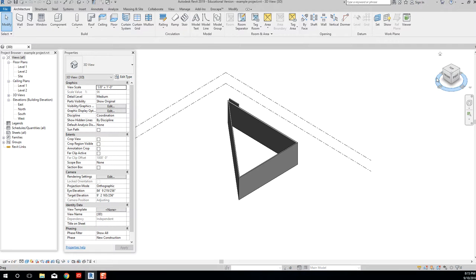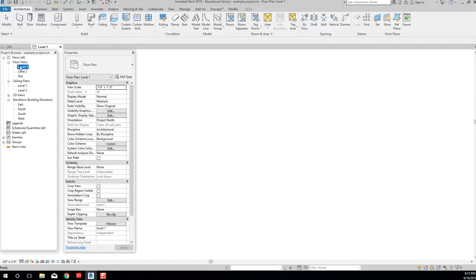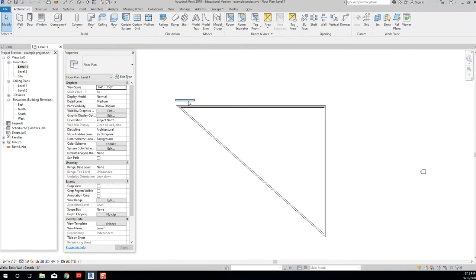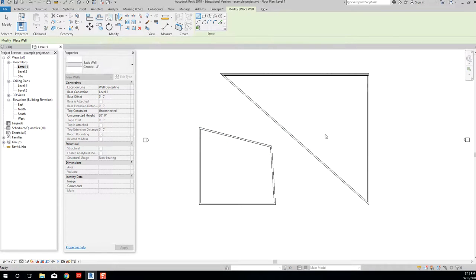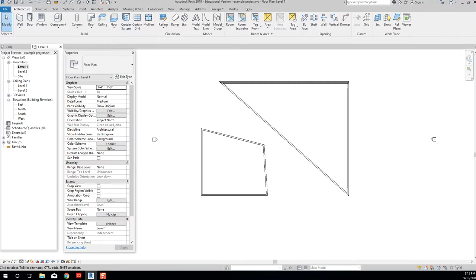So that new blank project didn't have a lot of these views populated because I opened it not using a template, right? And you can already see I was like, wait a minute, where are my elevations? Where are some of my other things? They weren't there because they weren't built into the template, and I wanted to use some of those things today. So I went to my other drawing that I had started using a template, like the architectural template or the construction template, okay? So I'm going to draw another little area here. Not so straight. There we go. Looks pretty good.